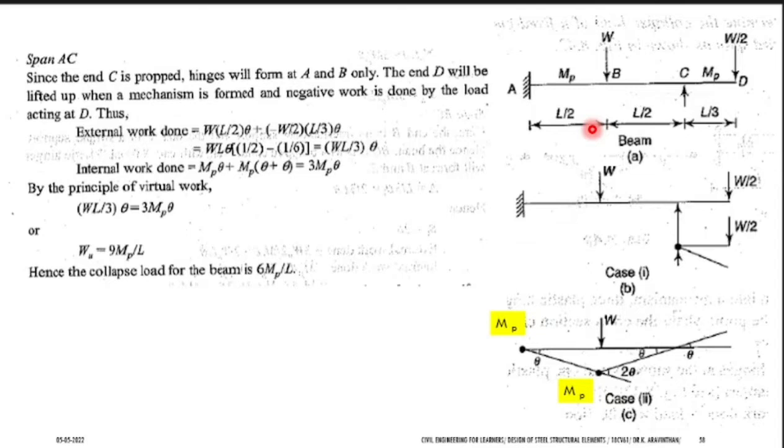Then you are having a severe earthquake. As a civil engineer, you can say which beam will break first. Then what will be the second failure? How will this break? Can you recognize the previous cases? A building is collapsing step by step. So I have shown you that, no. If you know this concept, you can say which span will break first, at what load it will break, and what will be next. Like that you can find the collapse load.